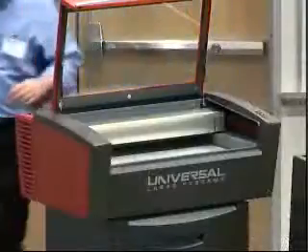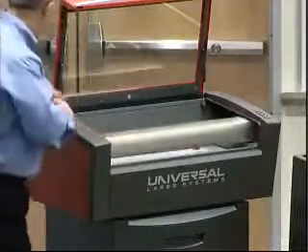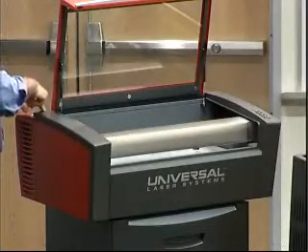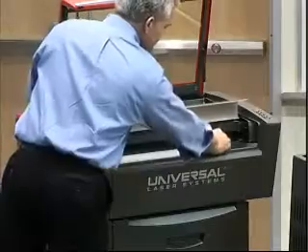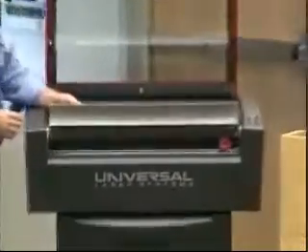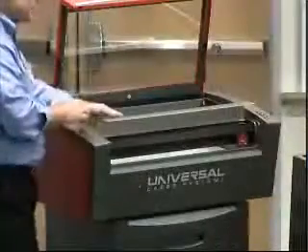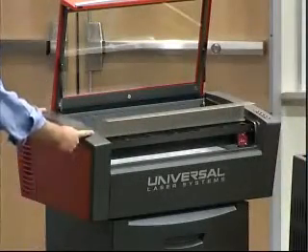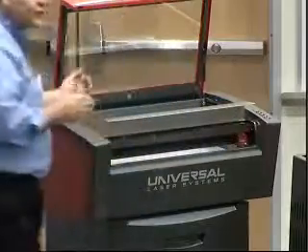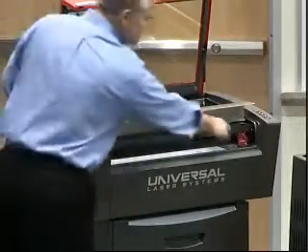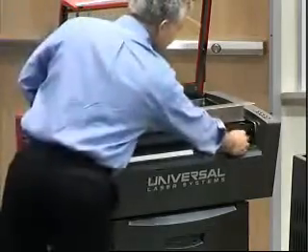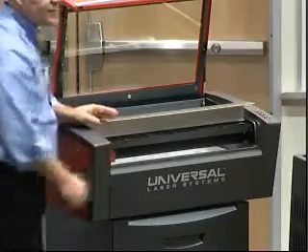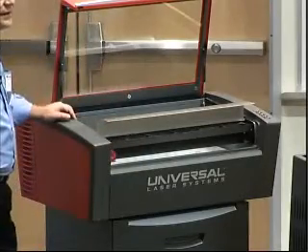That's probably due to alignment of the beam. This is where the beam is extracted from the laser. So if you're in the lower left corner back here, let me hit the usual problem first. When you're way over here, that's where the beam's traveling the furthest, right? It's got to travel this distance. So if there's an alignment problem with the mirrors, sometimes you don't end up coming right through the center of the final focusing optics. That problem can exist in different places. It can exist here, or it can exist there, or it can even exist at the very beginning.